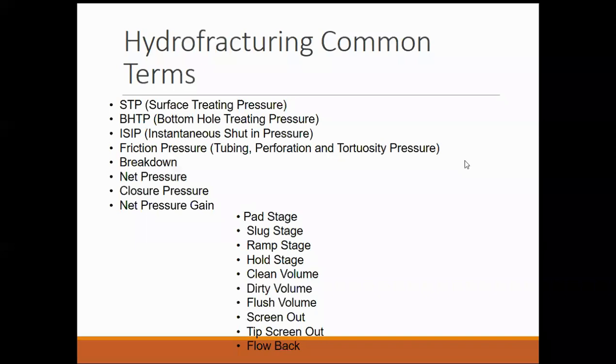This is a very important term. As soon as you are done with your frac job and you have flushed all the sand into the formation, you shut down your pumps. At that point, the pressure you see at the wellhead is called the instantaneous shut-in pressure. At the instant of shut-in, the pumps are stopped, the fluid has stopped moving, and all the friction effects of the fluid have been nullified. So that pressure gives you a good indication of the pressure required to keep the fracture open.